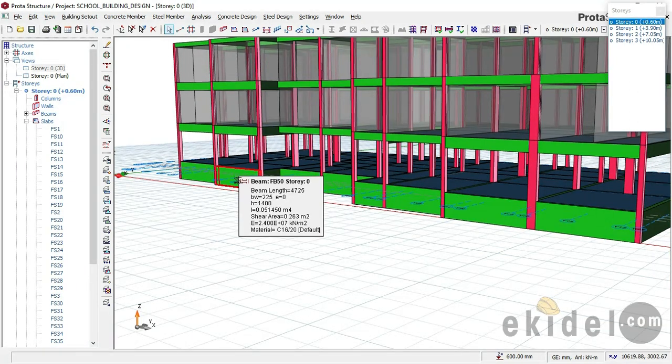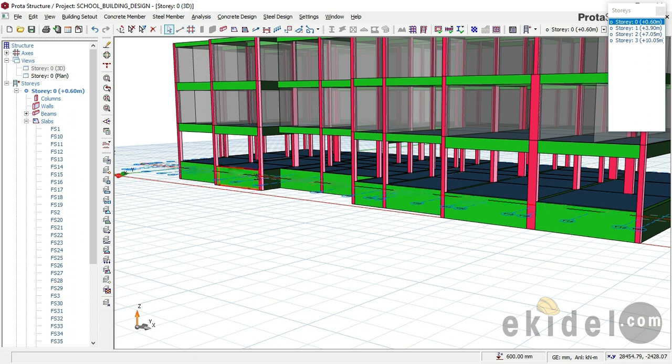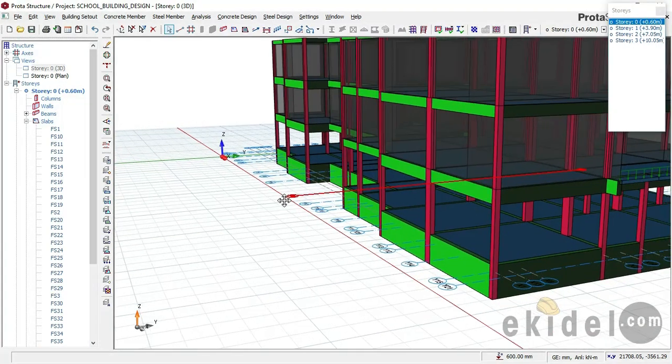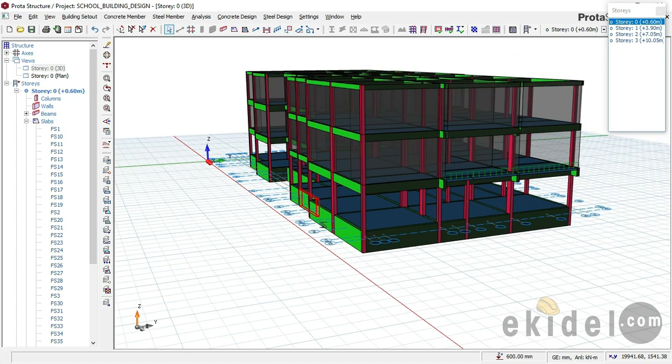The way we design a retaining wall is by using a toe at the bottom of that wall. So right now, since the beam depth of this raft is 1.4 meters high, I'm going to add a toe. The reason for that toe is to be able to resist what they call overburden pressure, or you can say active pressure, that will affect this beam at the bottom. So I'm going to apply what they call a toe on this raft foundation. Most people don't do it, but like I told you, we follow guidelines and what is there in the BS code. So let me show you right now what I mean by toe.